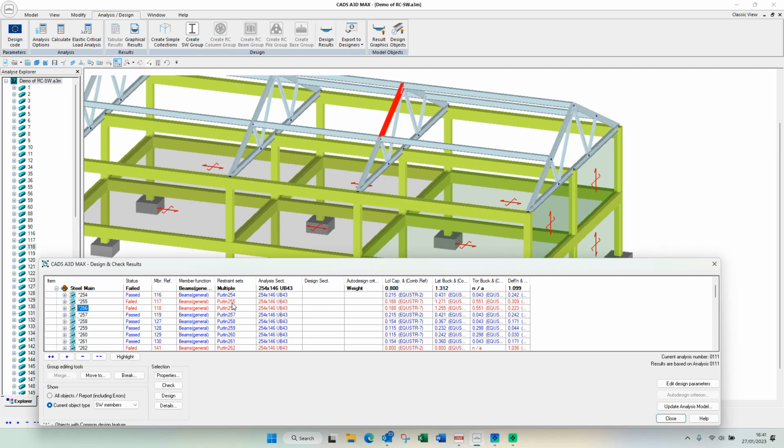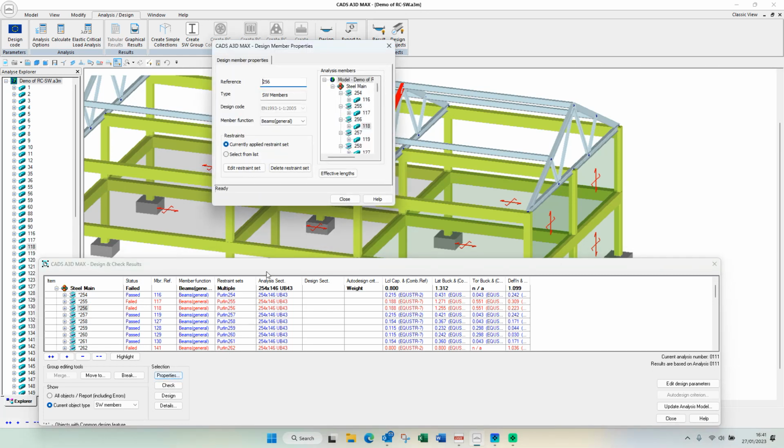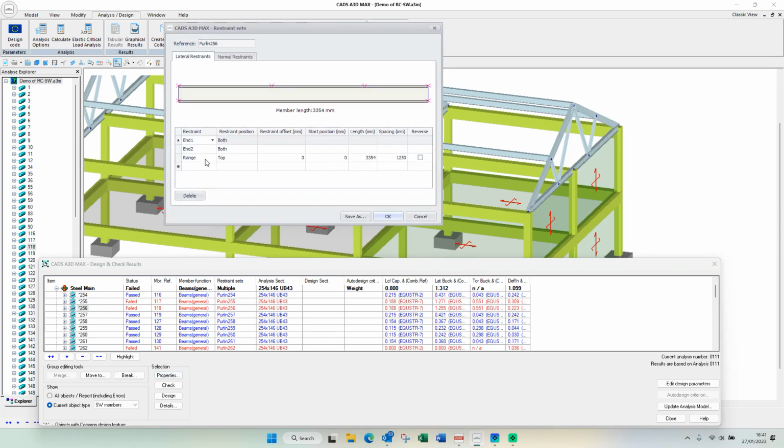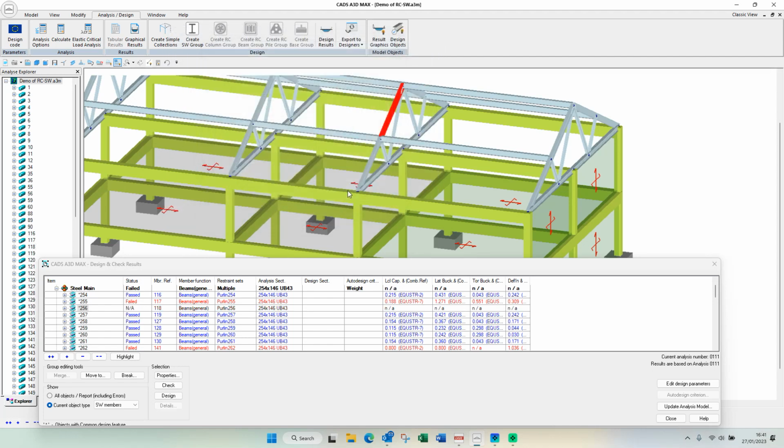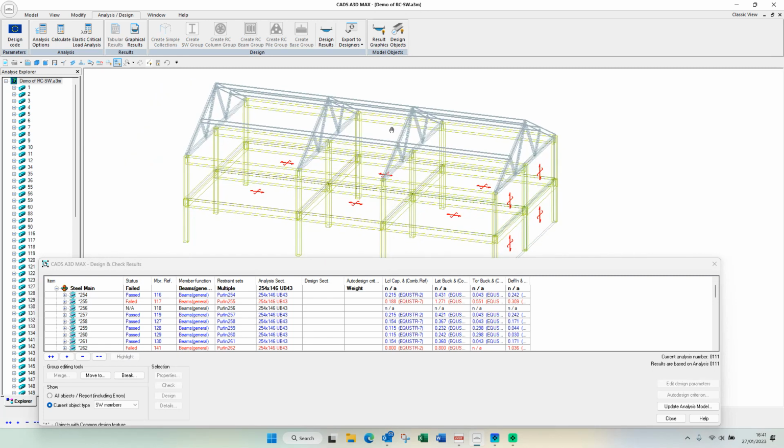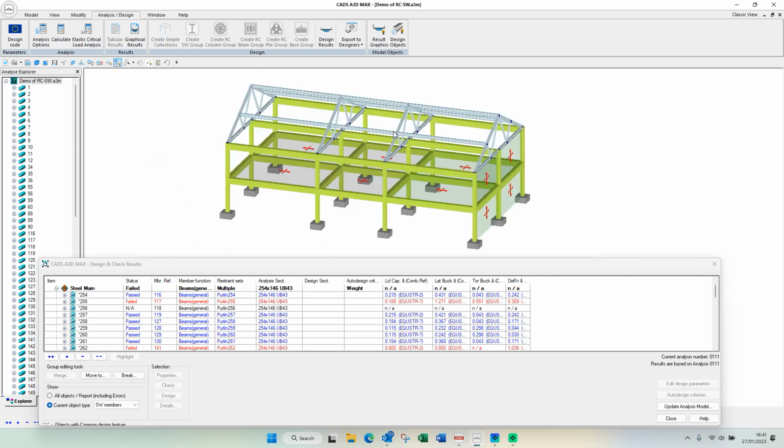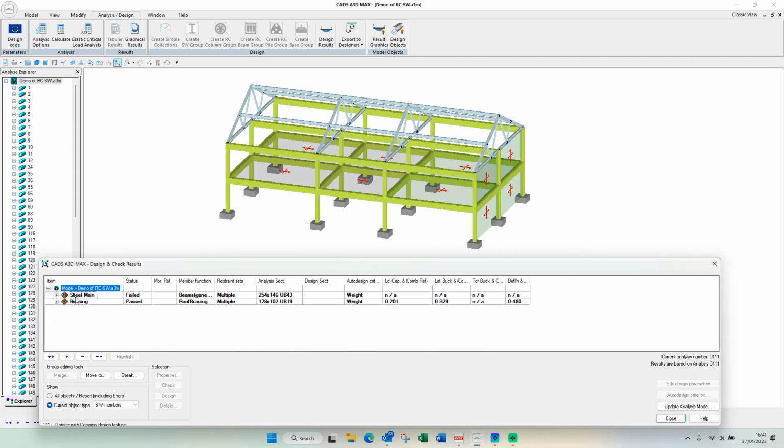I mean, one other way of working with this, you can see I've got this restraint type of purlin in here. That I did already. So I've set up a range of restraints on the top flange of this member at 1250 centers. Now you could change the pitch here, reduce it to get it to work. You could put more restraints in at certain positions, and you can indeed create several different types and put them in different areas of the structure. But failing that, if it's just sizing the member that's necessary, all we need to do is run the calc again.